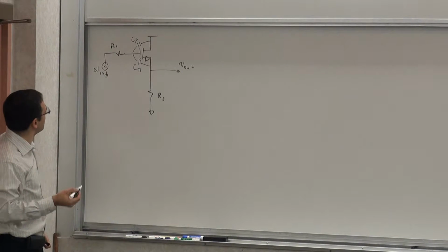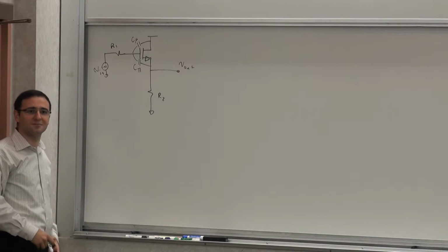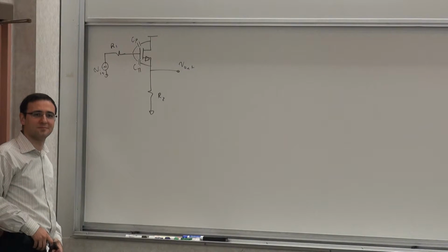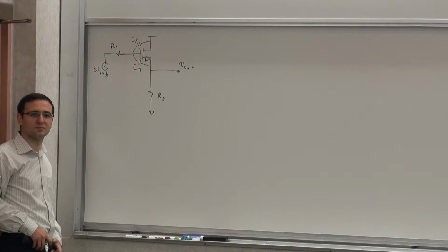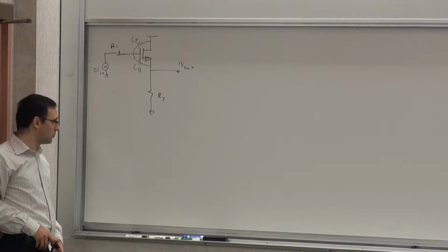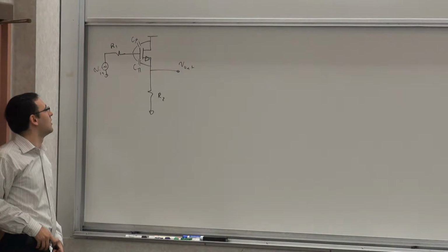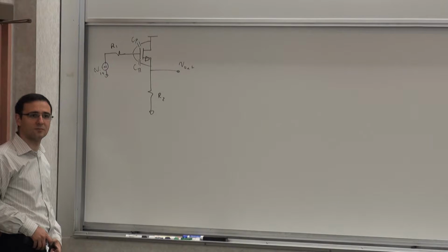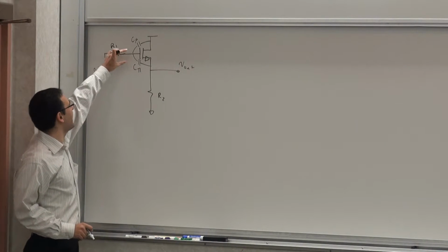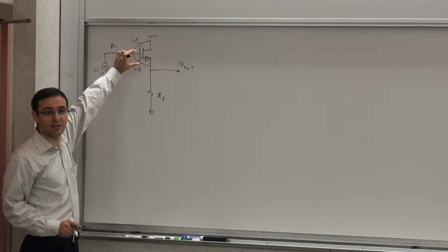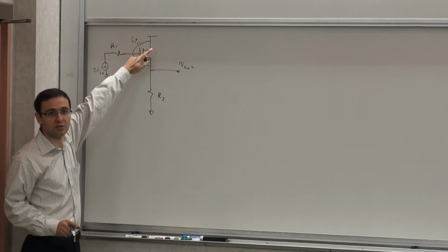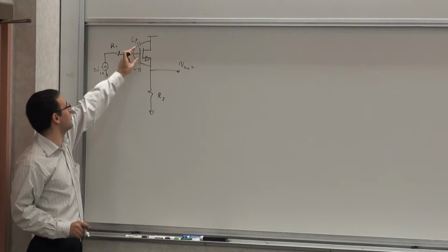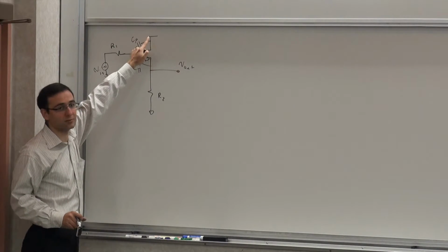Okay, so how many poles, how many zeros? 2 poles, correct. And how many zeros? 1 zero, correct. Only shorting of this one. You can't simultaneously short this and that and get a non-zero transfer function, because this shorts the input essentially and shorts the output. If you simultaneously short both of them, you short the output to ground.